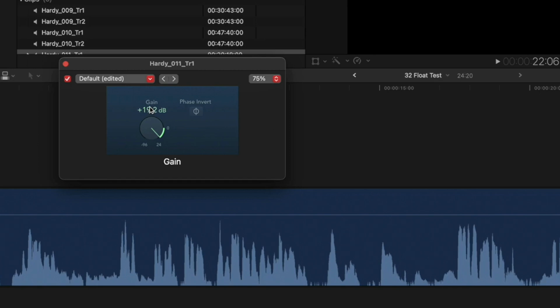Looks like we've hit the nail on the head straight away. We are unable to process Float 32 in real time. It is recorded internally to the 8 gigabytes of storage in the microphone. So as far as using it with external devices, in particular via Bluetooth, there's no way to do 32-bit float. My gut feeling is that it's processing at 24 bits and probably at 48 kilohertz. So it's nevertheless a good microphone, but for Float 32 applications and the wide dynamic range, it's only post-processing.